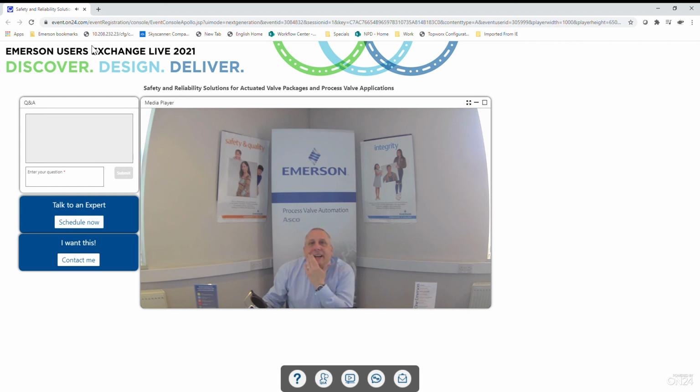So again, what solution should I offer? That's a good question again, but there are a few factors that dictate, for example, what flow is required. If you look at the RCS, the standard RCS has a higher flow than the ARCS in certain applications. And when we first looked at the live demonstration, I showed an ACS, which is an actuated control system. That can be tailor-made to your own requirements. We can put additional features on there. We can put lots of valves and basically make the circuit to anything you need. Whereas the RCS and the ARCS are designed in a particular way, to satisfy your requirements.